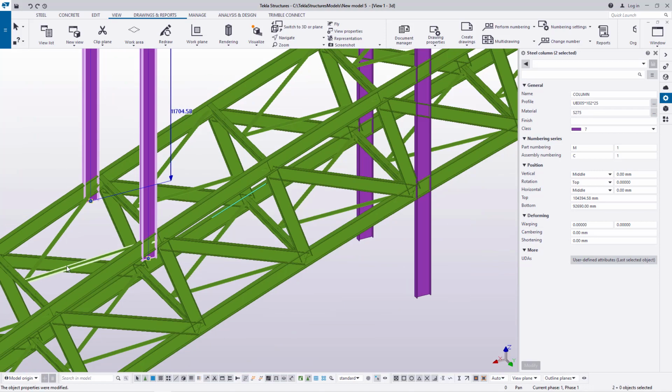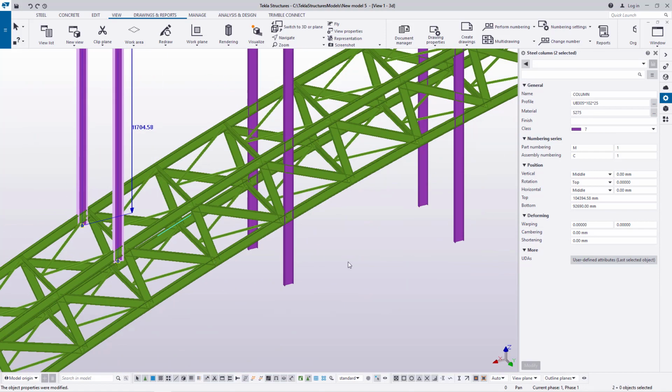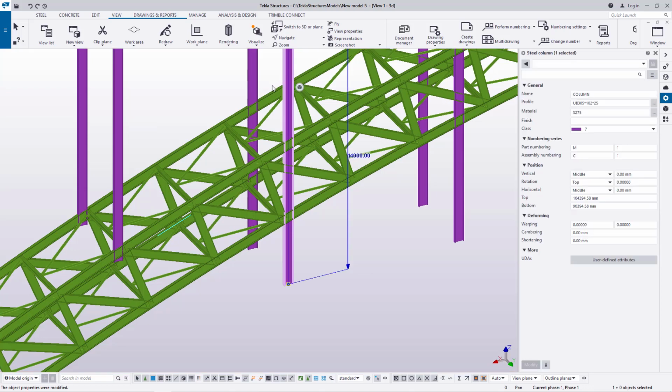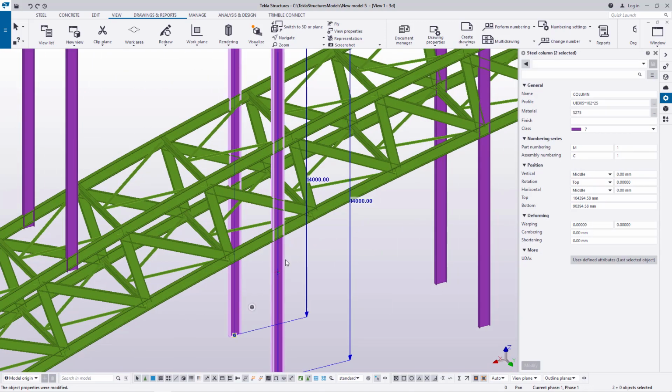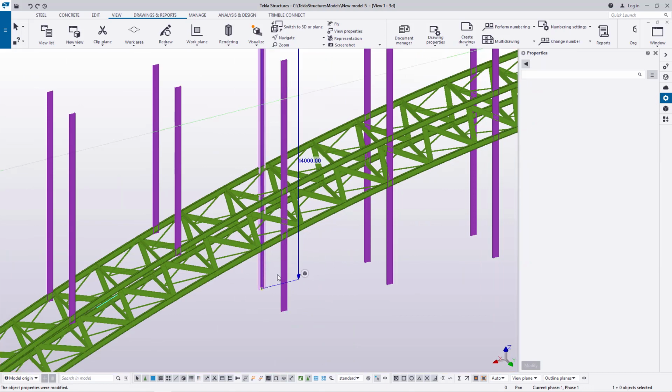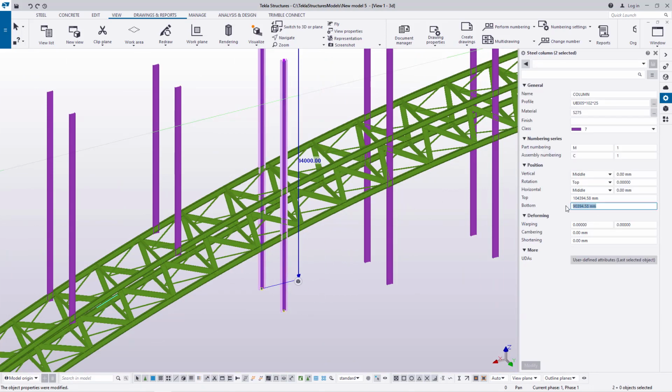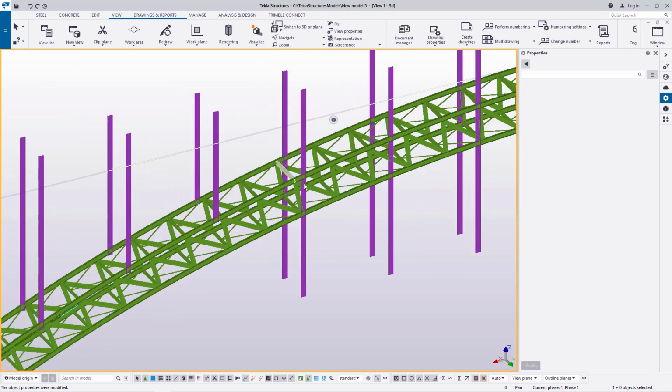That's where it belongs. It's not accurately on that spot, and you can still go ahead and modify it further by double clicking on it, but instead of wasting so much time there, we just go ahead and trim the others. Double click on that, and we'll feed here 94,990, and we'll click that, and right there it is. We'll go ahead and do the same thing here, that and that, and we'll change this to 96,900, and there we are. And that's how we trim them.